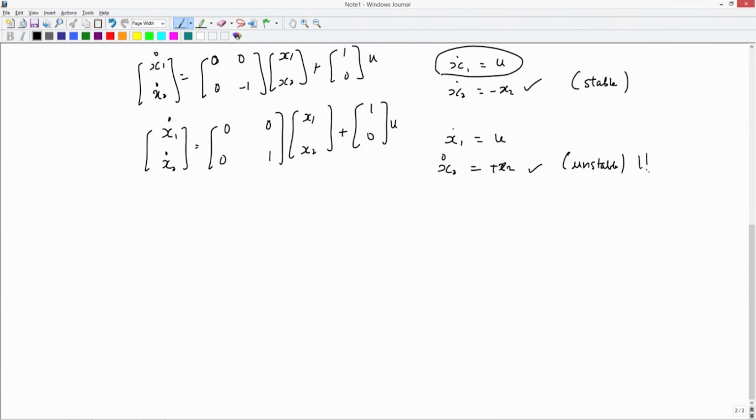So, there is some hope when the system is not completely controllable if and only if the uncontrollable part is stable by itself. Here I could do nothing with the system, because whatever smart kind of input I choose, whatever the best kind of input, my x2 is still unstable, which means that the overall system is unstable.